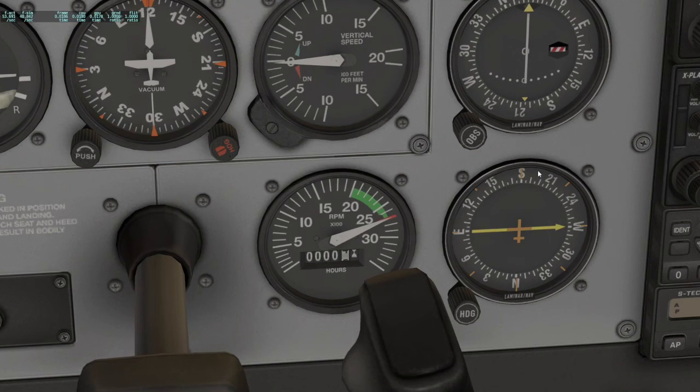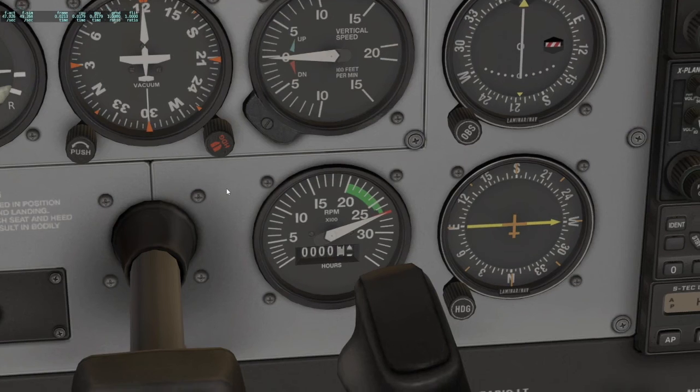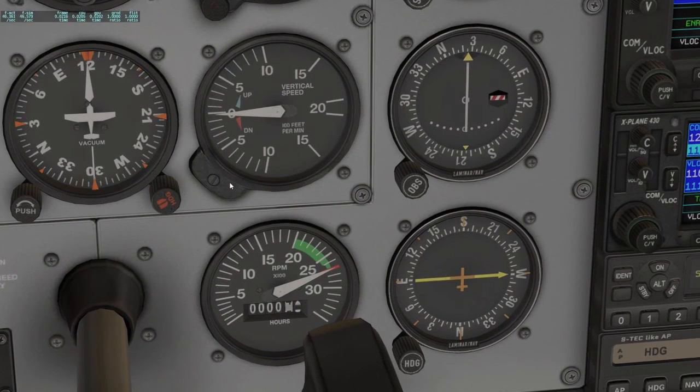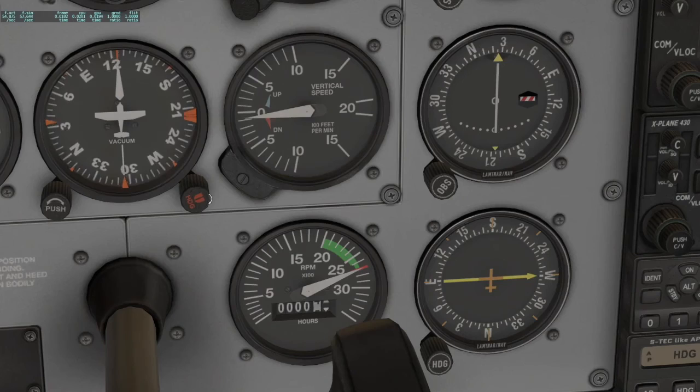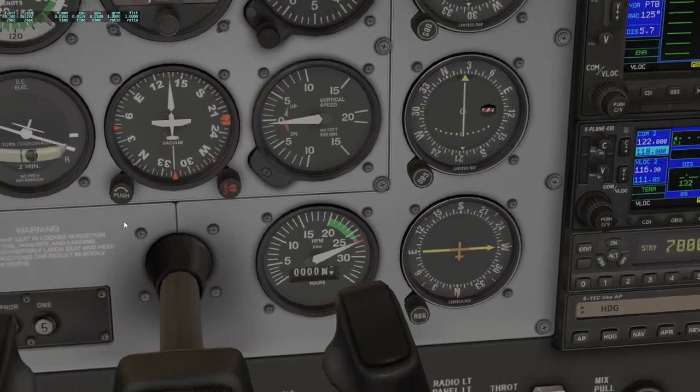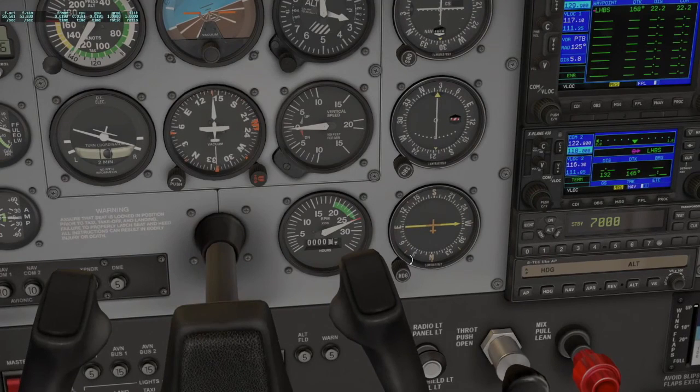What is the 45 degrees that way? Nothing to think about, nothing to worry about. Just look here, 45 degrees this way. Here's your little marker. That would be 225. So I need to turn right away to heading 225 to intercept that outbound radial. Here you go. I'm going to turn now. 225, using my heading selector for the autopilot.